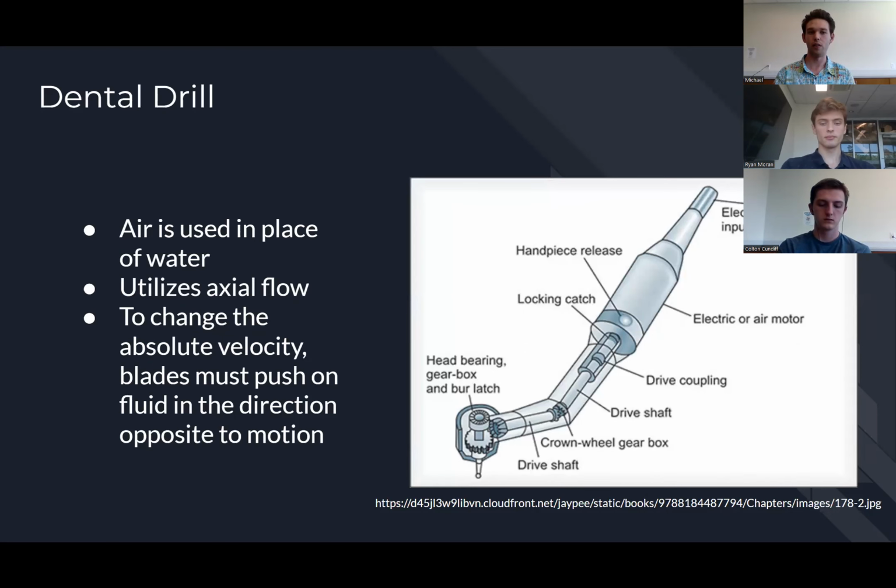And here we have a dental drill pictured at the right. And this is the type of drill that a dentist would use to fill a cavity or whatnot. And in this case, air is used in place of water, and it utilizes axial flow. And this case is special because to change the absolute velocity, the blades must push the fluid in the opposite direction of the motion of the blades.